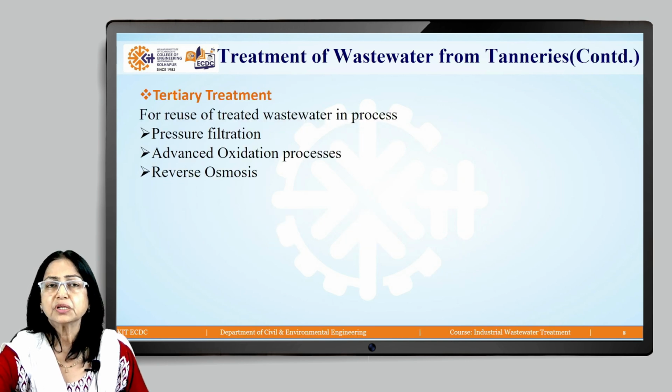Many times the tannery wastewater meets all specified standards for wastewater except total dissolved solids because of high salt content. A lot of salt is applied on the skin, which is removed during the process. So, all this salt ends up in the wastewater. Hence, wastewater may not meet the standard for TDS of 2100. In such a case, wastewater may require tertiary treatment.